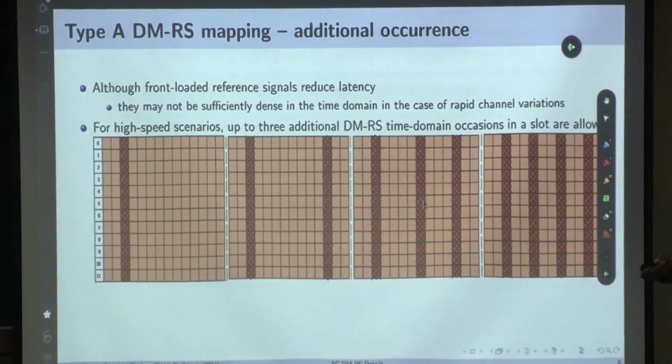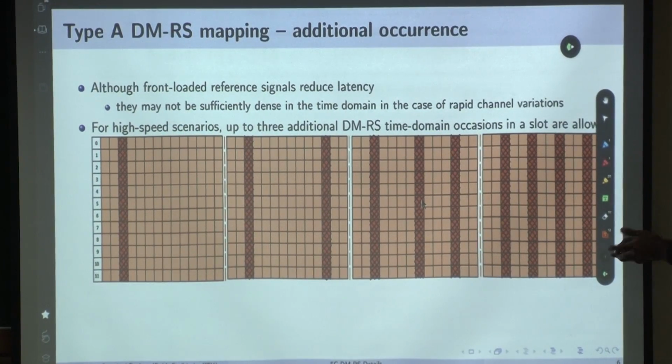Your user's data rate is reducing, because all this will be accounted for during rate matching. Rate matching will tell you how many resource elements there are per PRB. You remember that formula; in that formula, all these were accounted for as additional overhead. So this is that additional overhead, which I could not tell you about at that stage. This additional overhead is going to reduce the number of resource elements.